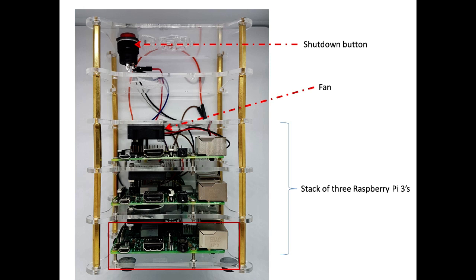So what I've got here is a stack, an acrylic stack with metal rods in between, threaded rods of course, and they allowed me to create this stack of Raspberry Pis. They didn't come with a hole for the fans, some do, and if they don't, as in my case, then all I did was lay out where I needed the fan to be, drill a few holes, and then use that acrylic layer as a template for the other layers. One word of warning: if you're drilling out the bigger hole using a hole cutter, remember it's acrylic, and acrylic doesn't like being melted. I found that out the first time I did that, so I wasted a layer.